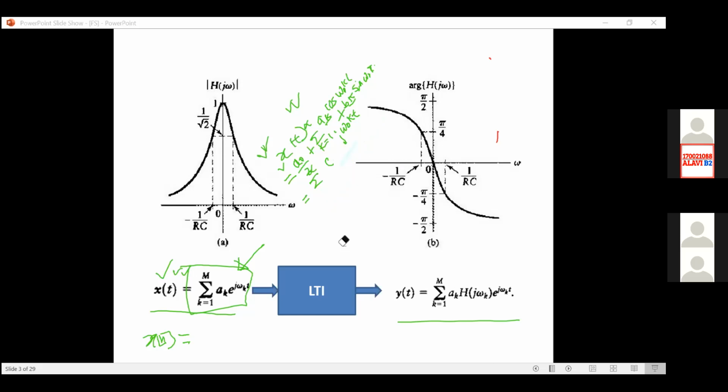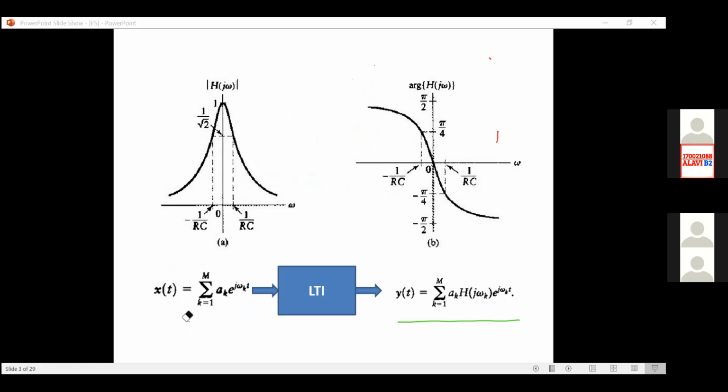If we express our periodic signal in trigonometric form, then your constants will be real and your signal is also real. And if we express it in exponential form, the Fourier constant will be complex, and your k Fourier harmonic should be extended from minus value to plus value. Another thing is that your Fourier constant will appear in complex conjugate form. So with this assumption that we are expressing our signal in this way, now the question is what?